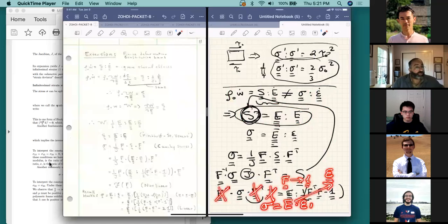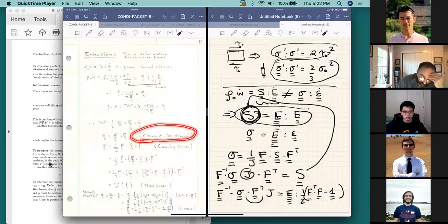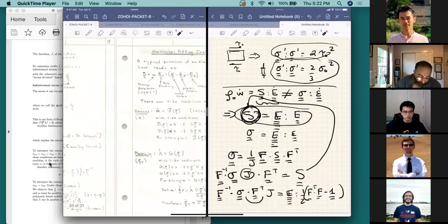So it's the go-to constitutive law that's very useful in industry when people want to extend simple linear elastic laws to moderate strains. So moderate strains might be 5, maybe 10% strains. So basically things that are pretty big, that are noticeably big, this is the constitutive law that people use. And this is sometimes called the Kirchhoff-Saint Venant constitutive law. And you'll see this in many finite element packages and all kinds of other literature. It's widely used. So that's the first one.